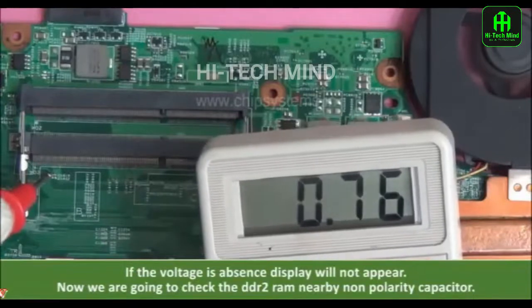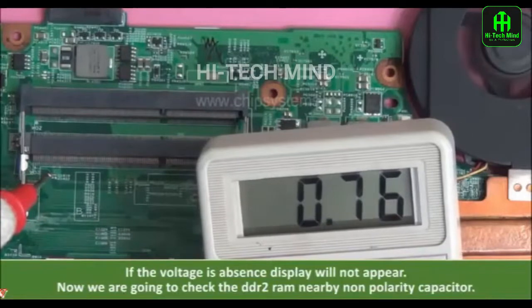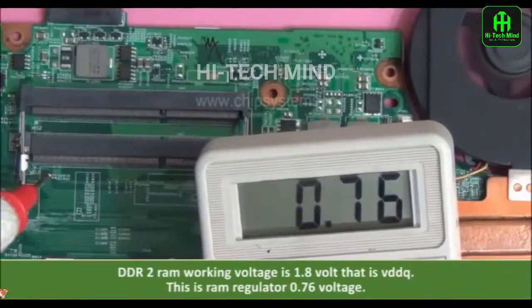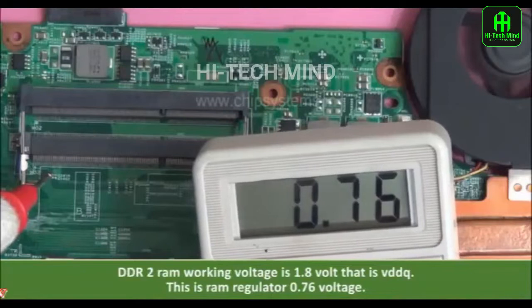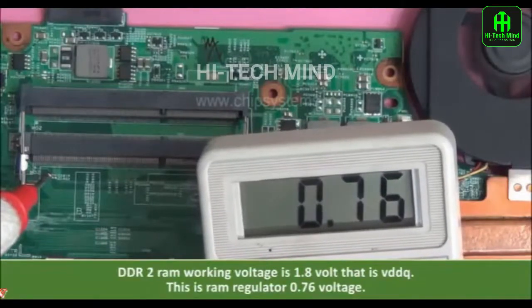Now we are going to check the DDR2 RAM nearby any non-polarity capacitor. The DDR2 RAM working voltage is 1.8 volt, that is VDDQ. This is the RAM regulator 0.76 voltage.